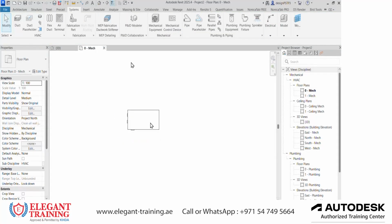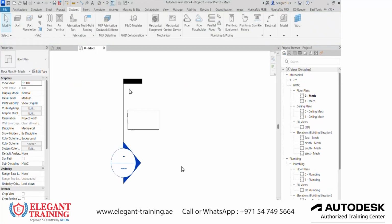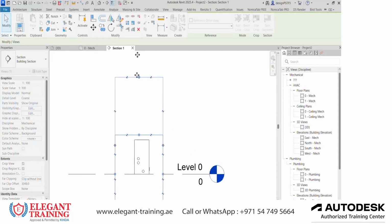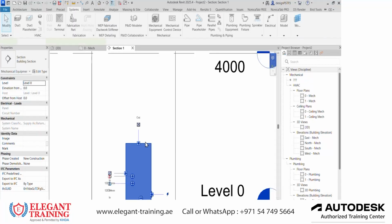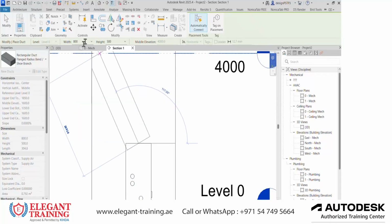Okay. Then the best way is take a section. Open the section. There. Now I can start draw from here, like out. When you draw, you can draw the duct like this. Showing single line, so change this to detail level fine. Okay. Showing 800. So if I need, I can also reduce it. I can also go above that one also.